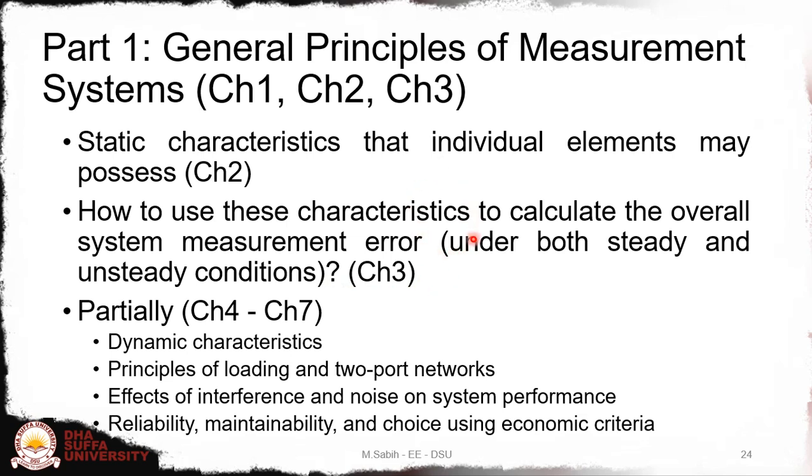After completing these two, you will be able to deal with any sensor. You can devise the characteristics. You can identify how the sensor is behaving, whether it is linear or non-linear over the range, and in case of any environmental disturbances, how to take care of it and make small compensation, either with circuits or software, so that the overall measurement is accurate or correct.